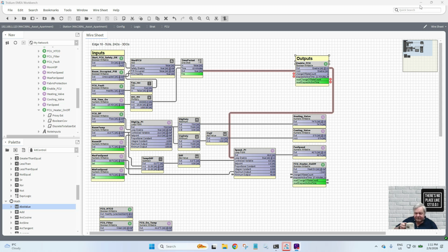Right, I've got my drink, but I'm still no wiser. So we're either going to use a heating valve, 0 to 10 control, a thyristor would be 0 to 10 control, and the heater on and off, the binary, is not 0 to 10. So we need to put some sort of selection in there of whether we're using analog or binary for heating.